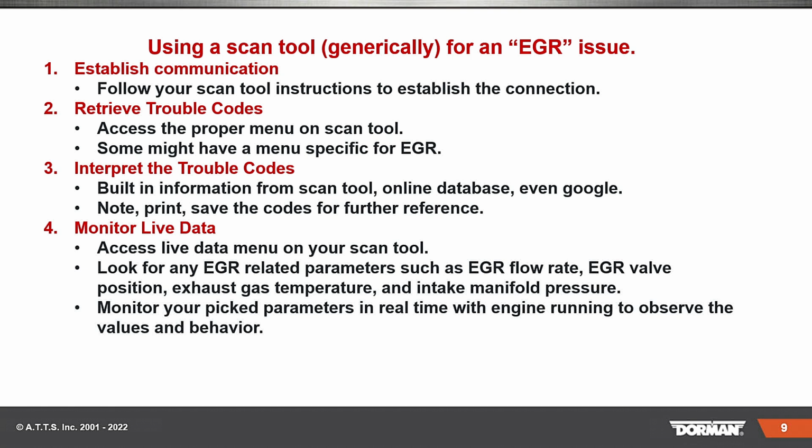Of course, the next big thing that you want to do is interpret the trouble codes. Depending on your scan tool, if you're on a laptop or whatever base you're into, there's a lot of memory in a lot of these scan tools, so utilize that if you have a lot of information there. Don't forget, you can go online. I even put Google, and once in a while I go to Google. I work on so many different models of engines and vehicles that I don't always have access for everything.